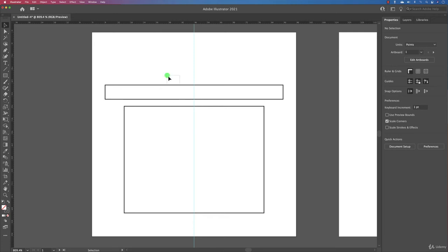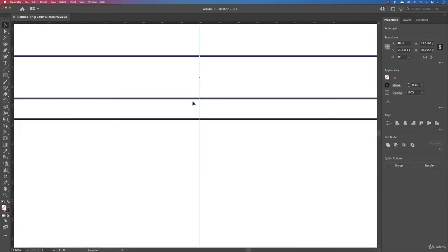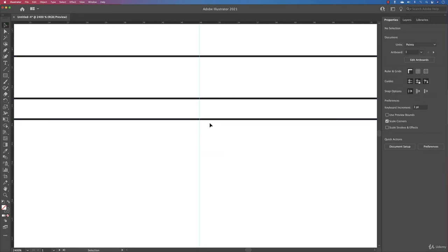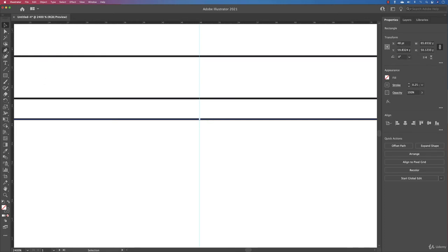It's pretty easy. Select whatever you want to select to create it, and then go to the pen tool and just add an anchor point here. Notice you need the plus sign. I can do this one, but it's not happening. You notice I cannot find the plus sign. So I'm going to deselect, select only this one here, go to the pen tool, come very nicely. I can see the plus now. If ever you don't see the plus with the pen tool, it means the object is not selected.